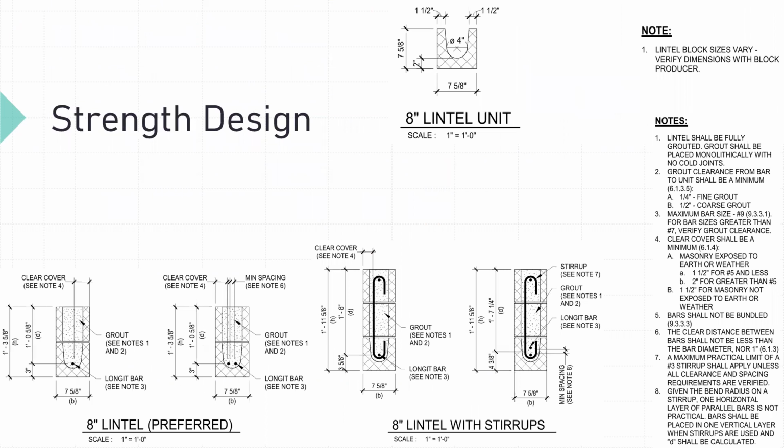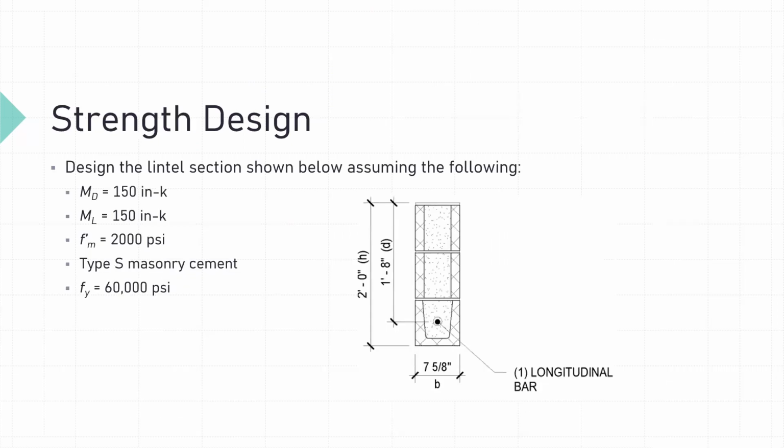Again, if we are using U-shaped lintel units, make sure the reinforcement fits in the lintel. I've gone through a lot of mold drawings, so if you have a question, reach out. I'm happy to go through it with you. There are a lot of requirements in terms of grout space, whether we're using fine grout or coarse grout, our clear cover requirements if we're exposed to earth or weather, fire rating requirements on where that reinforcement needs to be, and clear distance requirements. No matter what, we want to make sure that reinforcement is actually fitting in whatever it is we're designing. If you have questions about that, again, I'm happy to help.